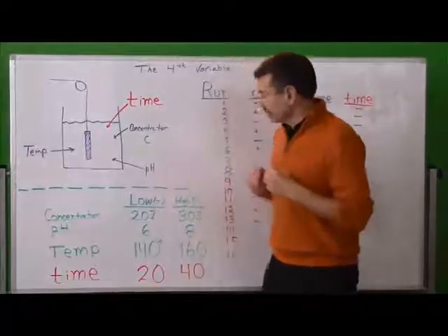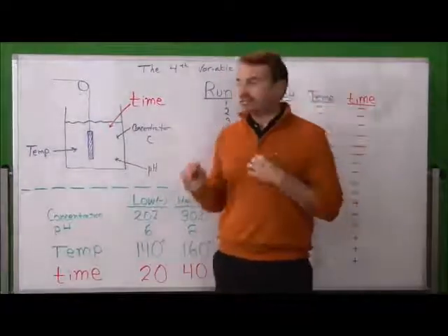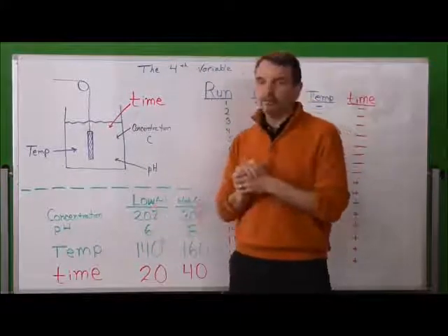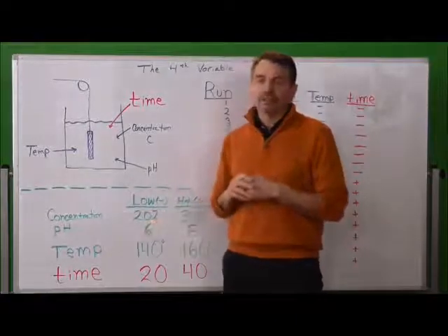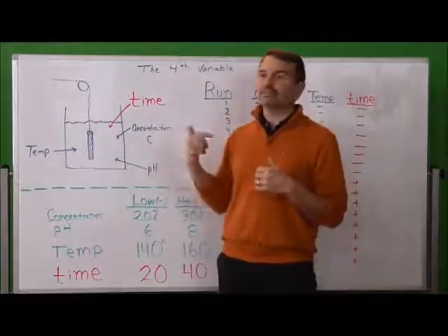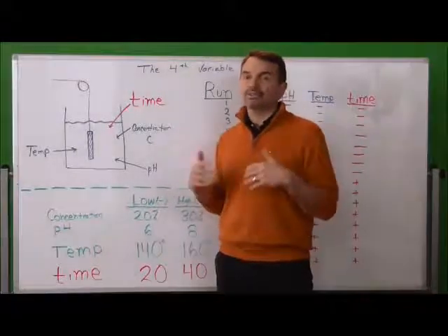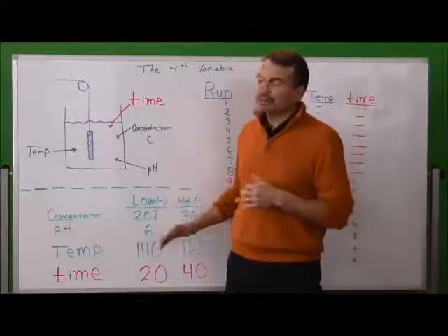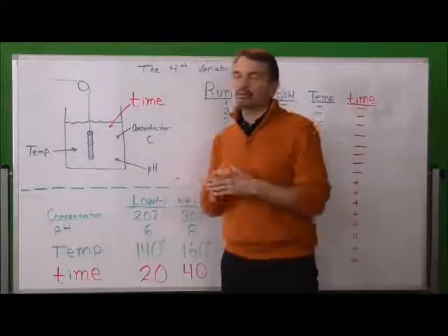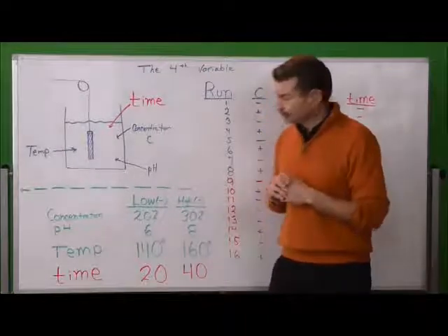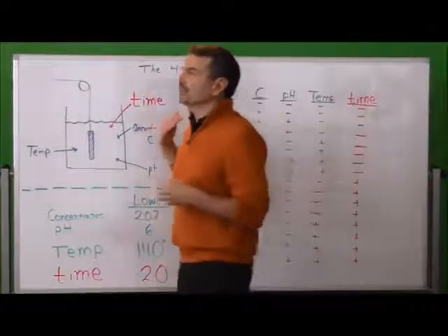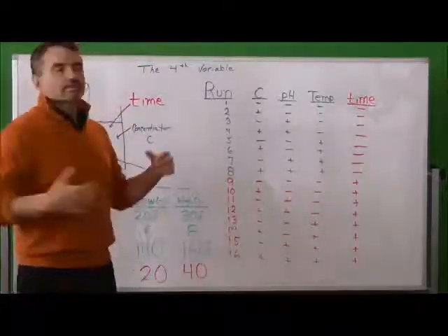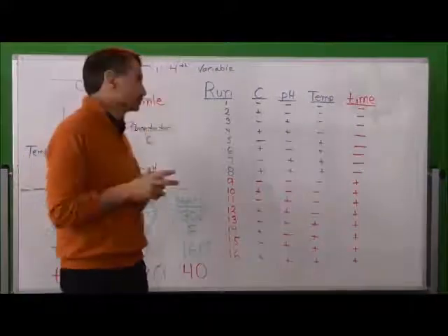Well, there's a magic little formula that you can do off of it. When you have 4 factors at 2 levels, the high and the low, you take the 2 levels and raise them to the number of factors, or 2 to the 4th, and you come up with 16 runs for a complete full factorial DOE, as was done in this particular example, and what we're going to walk through. So let's go over to the design on the other side and look at very basically how it was set up and how it was done, and then we'll switch over to the analysis of the cube plots.